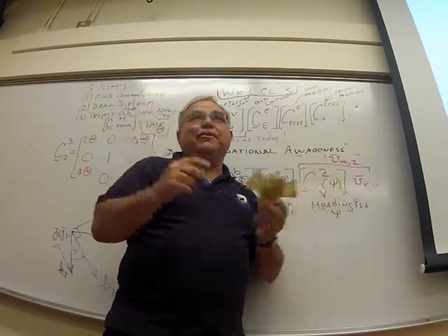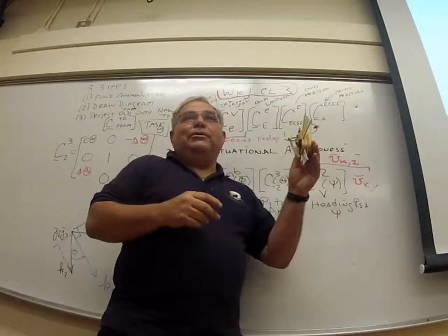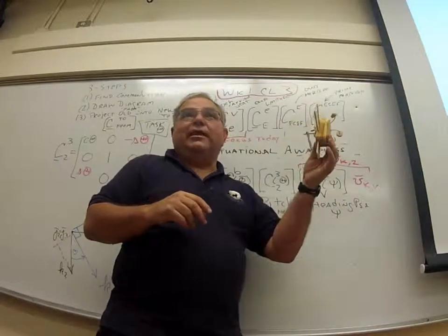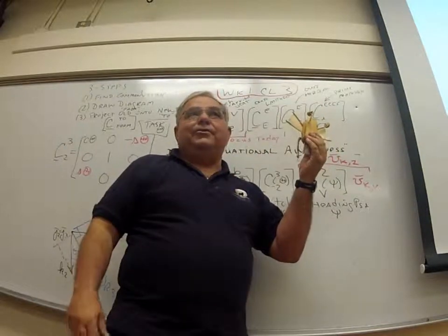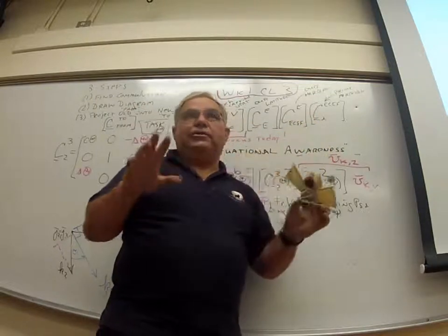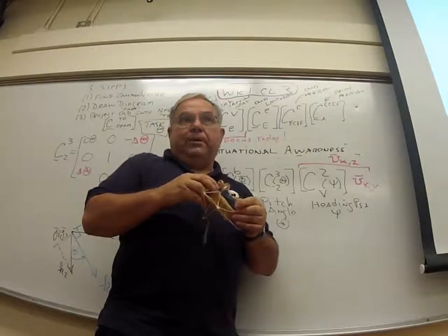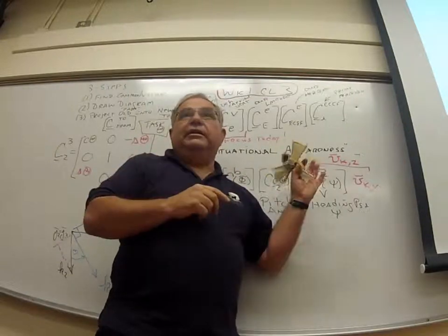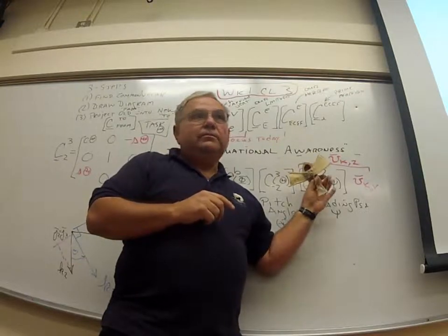But you can't show them pitch, angle, and roll if you're going straight up or straight down because your heading is undefined and your roll angle is undefined. All you know is your pitch is plus or minus 90 degrees. That's called gimbal lock. And we'll have a whole lecture on gimbal lock when we talk about quaternions next week. But it's a crucial flaw in this system that we've built together. But this is the system we have to live with.